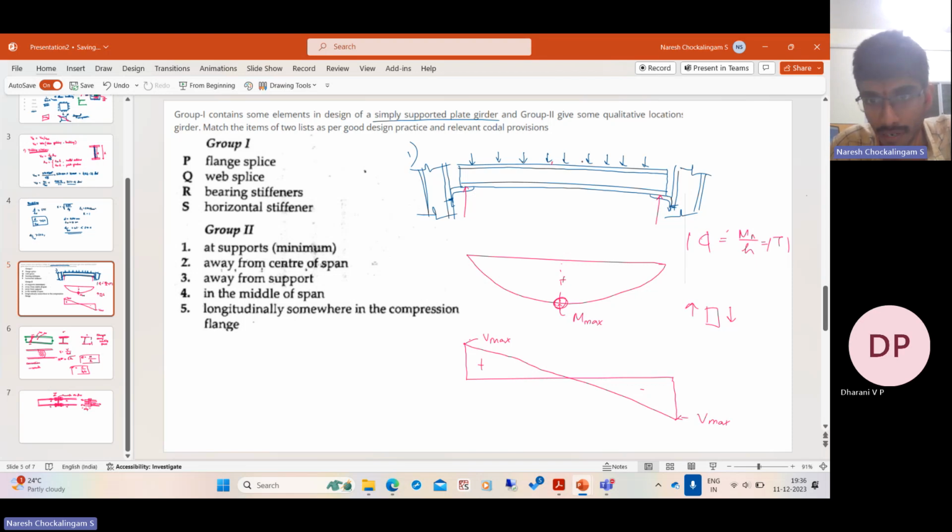Why? As I said, if you put it, there is no shear transfer. It will transfer the force, but there is no shear transfer between the two. It does not make sure that plane sections remain plane and all that. So you cannot use the moment of inertia formula. The bending moment capacity of a connected section is greatly reduced. It starts behaving as two parallel beams or something.